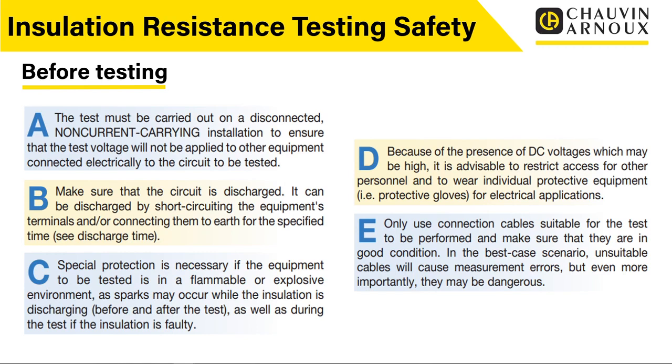So you do need to be very, very, very careful when you're actually applying insulation resistance tests, that you are in control of the whole test area and you've considered the full implications all the way through the installation for you actually carrying out that test. So there's a few pointers here that we're just going to go through, really just to give you some ideas of what we should do before we carry out insulation resistance testing.